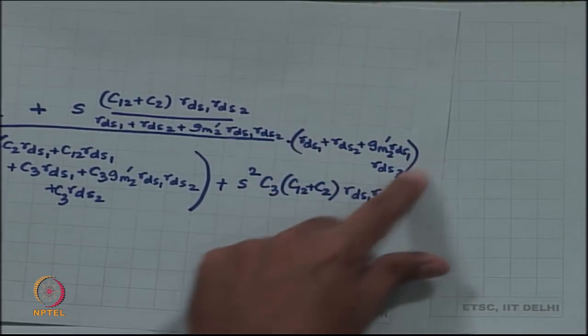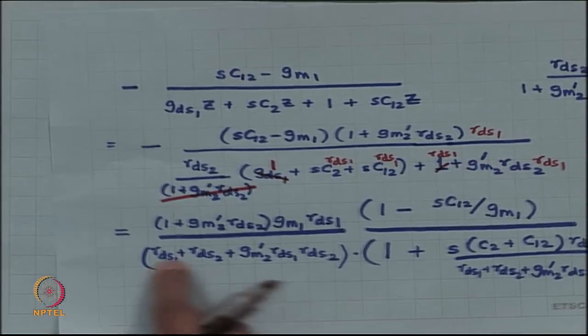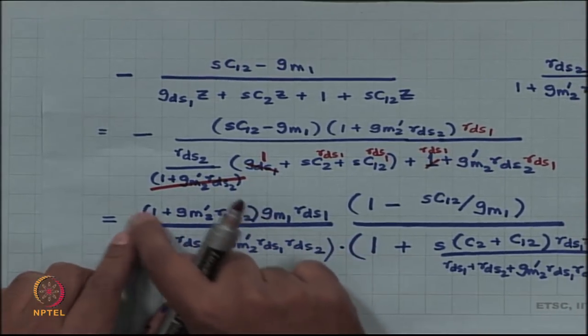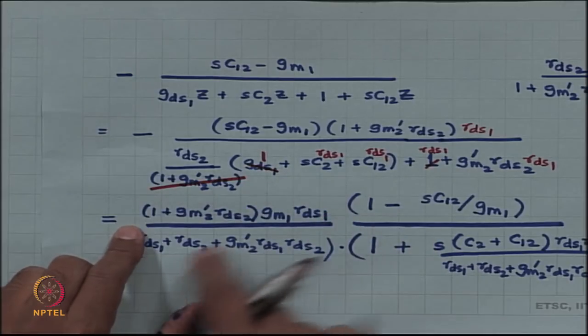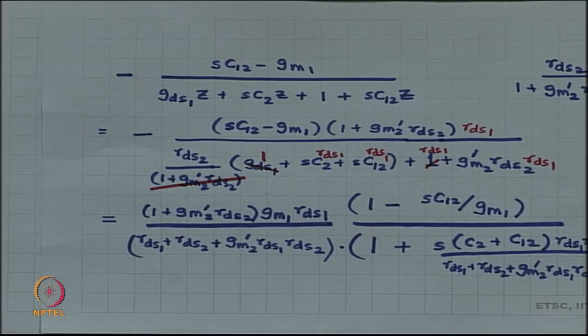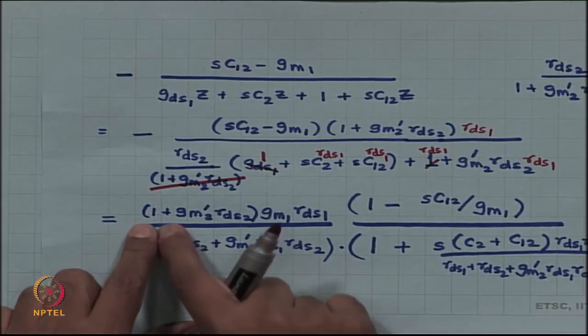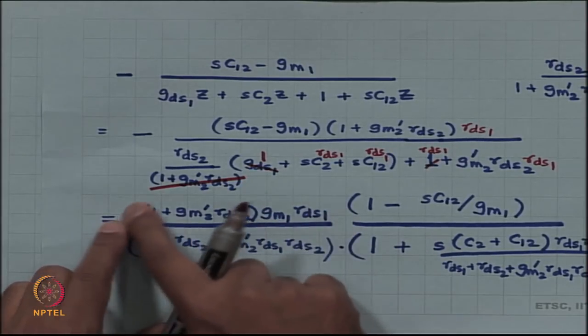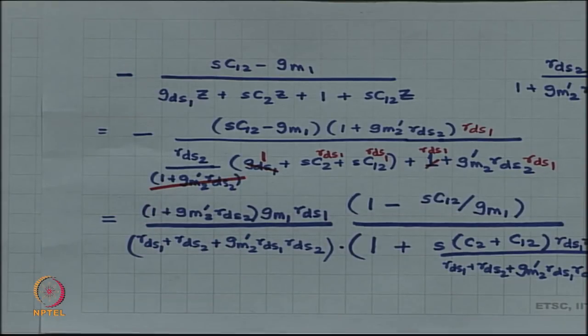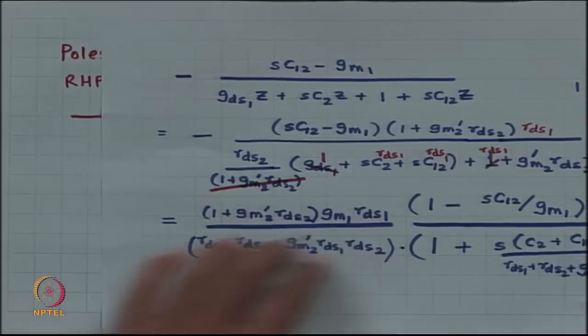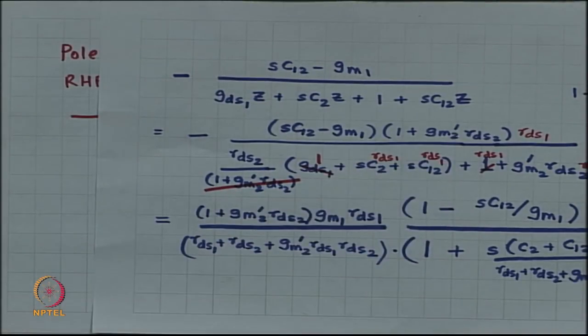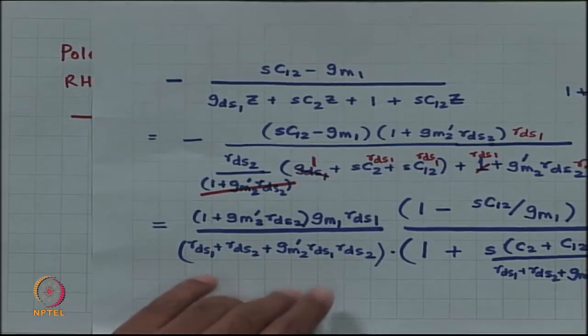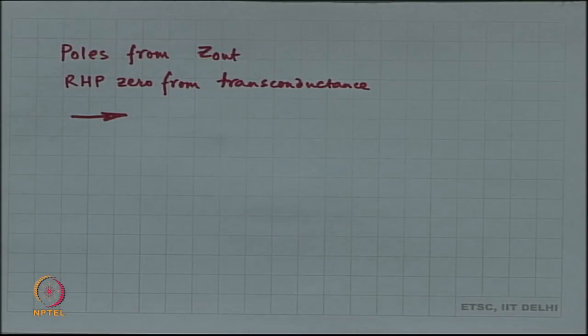This quantity, this DC term cancels out with this denominator, which means you only need the numerator from the transconductance, and that is your answer. Overall voltage gain at DC is just this much coming from the numerator of the transconductance. You do not even have to look at the denominator, it cancels out with the output impedance. Okay. So, that is also something interesting. In any case, let us assume you know the DC stuff, the DC stuff is easy to do.